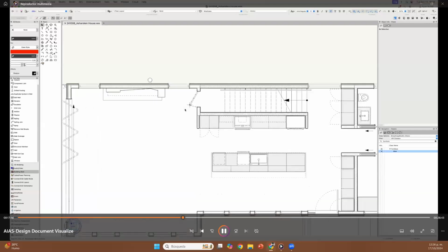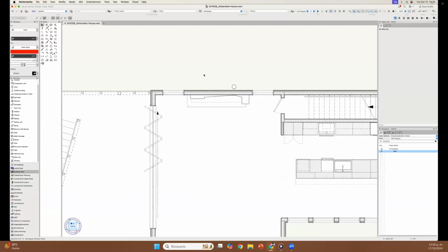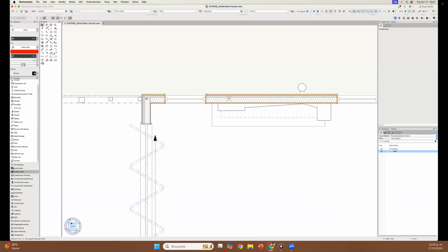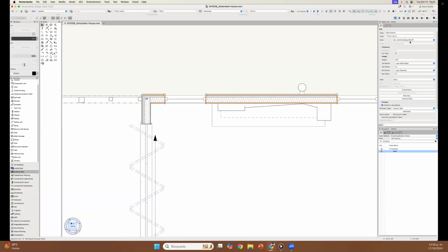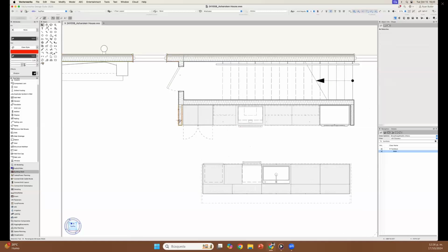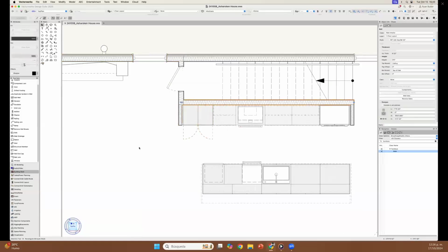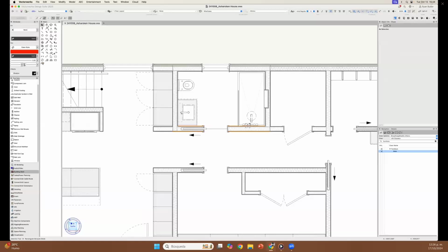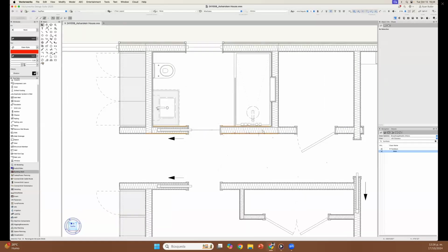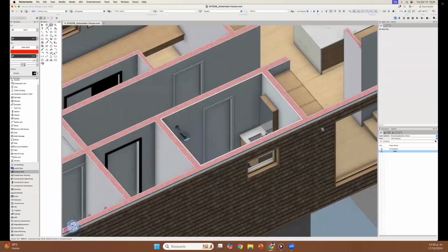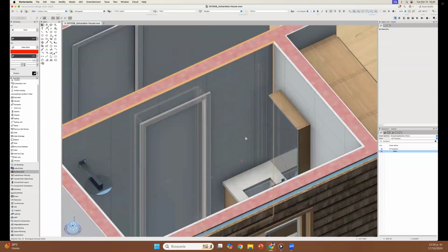Looking at this project, it's very simple when you look at the wall styles and all the other insertions. It's that wall style we were dealing with before. It's the 2x6 wood siding. Then there's other wall styles that I have for interior walls, like a 2x4 one or 2x6. And then I also added some wall styles that have tile on the inside. And you can see that in 3D, like so. So you can see that tile there.